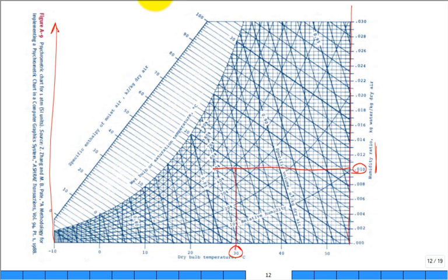And how many temperatures did we have? We had dry bulb temperature, wet bulb temperature, and dew point temperature. And how many humidities? Humidity ratio and relative humidity. And then we also are interested in the specific volume. So what is this chart when you get good at it? Let's say this is a known humidity ratio and dry bulb temperature. You can get the other ones. Now it's a little tricky, but let's take a look.